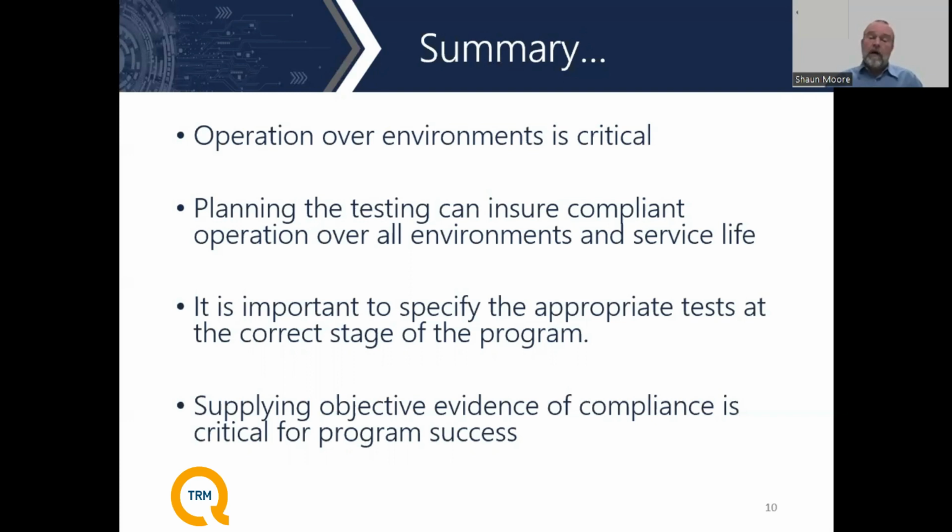Planning the testing is actually quite important, to determine which tests are appropriate at which stage of development. It's not always appropriate to test for every parameter on every part being built. It's not very cost effective. It can actually damage the parts because some of the testing that is done to verify some of the environments, quite frankly, is destructive. So we have to make sure that the plan is set up to test the appropriate feature at the appropriate time on the appropriate part.